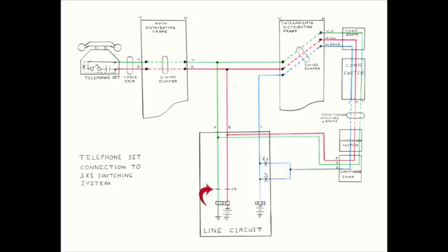In the diagram, the dashed line represents a break contact of a relay. The path through the break contact is closed, that is, passable when the relay is released, and open, unpassable, when the relay is operated. The X indicates a make contact of a relay. The path through the make contact is open when the relay is released and closed when the relay is operated. The line relay is operated on originating calls only to initiate a dial tone request. It operates over the loop from the calling telephone set.